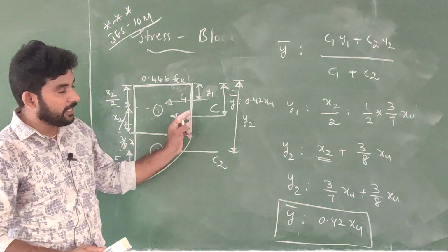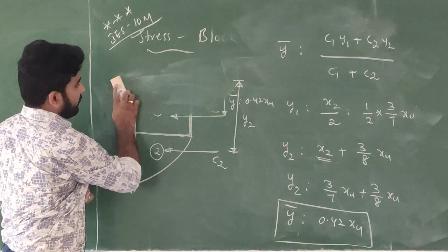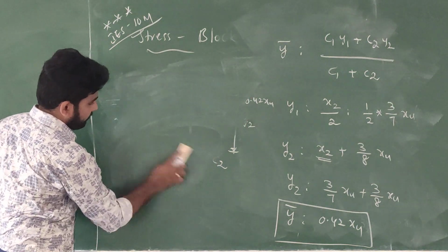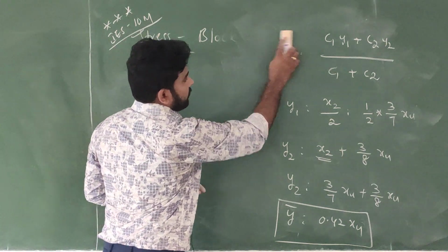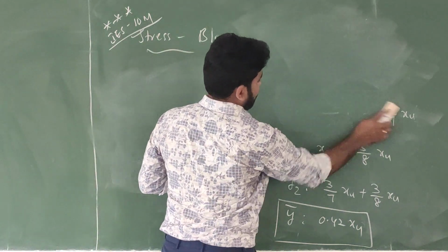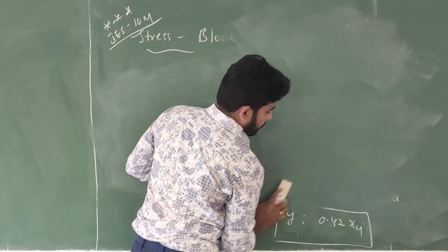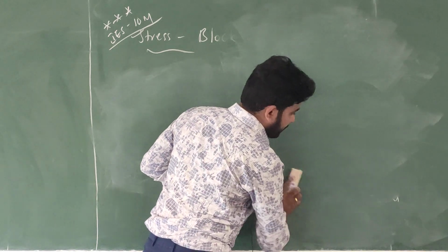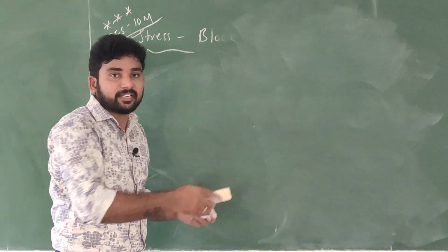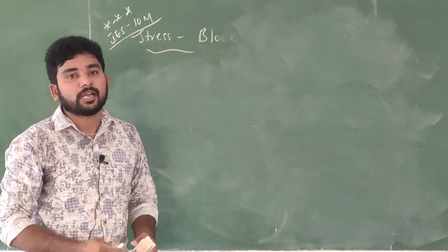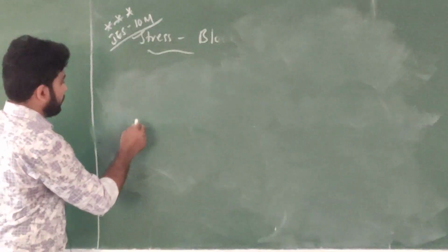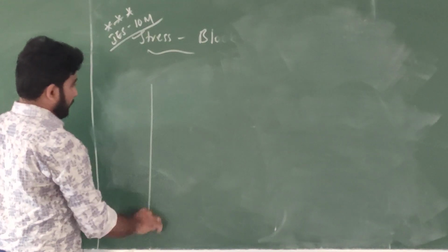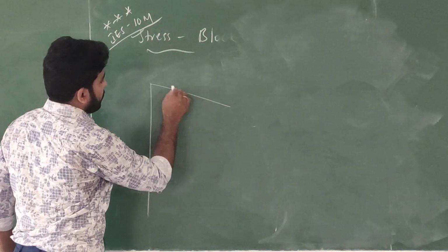Why are we determining this xu and all? I will show the diagram. So we determined the compressive force, and also where exactly this compressive force is acting. Now I am drawing the same stress block.